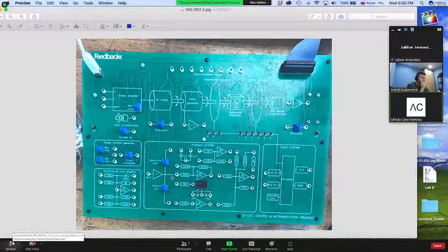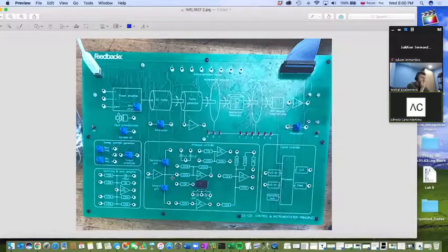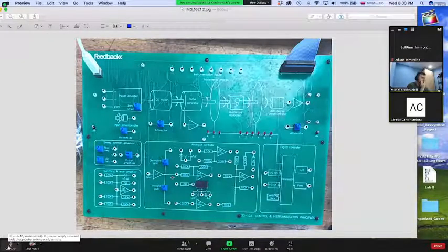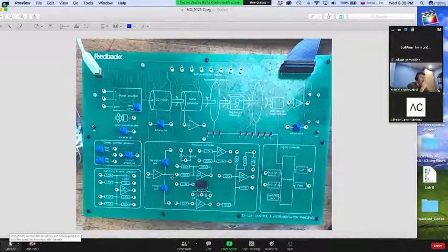elements. But if not, you set the attenuator to a low value so that you have space to turn it to the right and therefore increase the signal going through the attenuator, and that will correspond to increasing the gain. You usually don't fiddle around too much with the feedback resistor in the summing and error amplifier. You usually start at a value and leave it alone, and all they ask you to do is increase the attenuator. Which means more signal is going to go through as you turn the knob to the right. So that would correspond to actually increasing the gain.